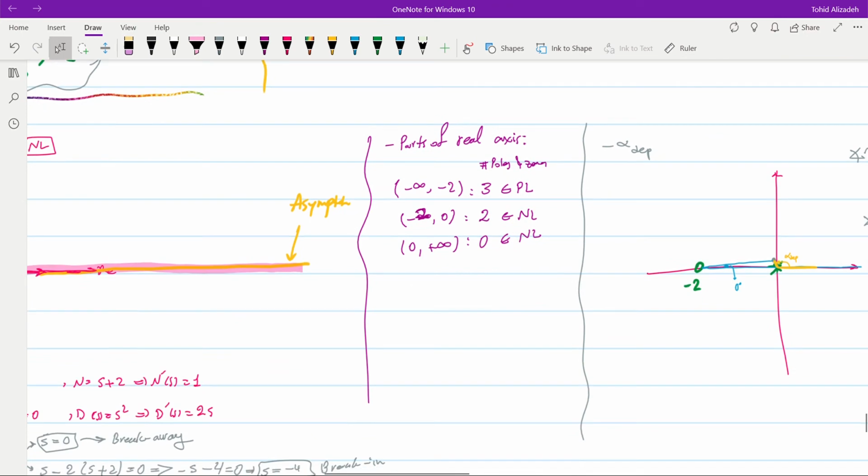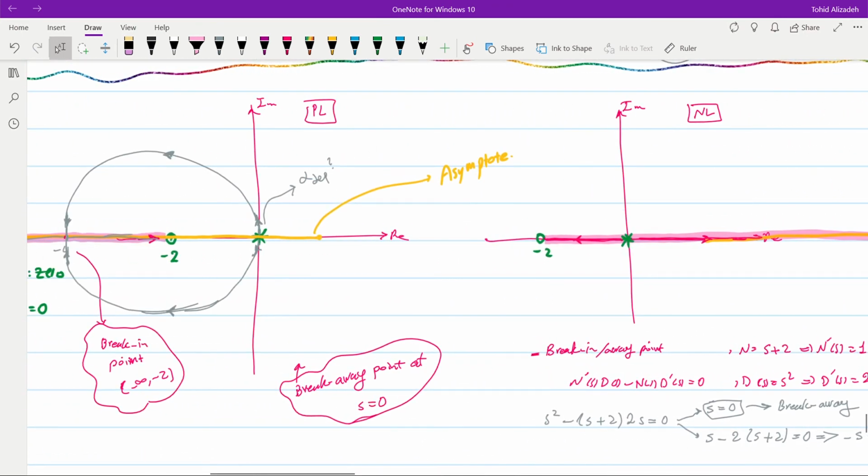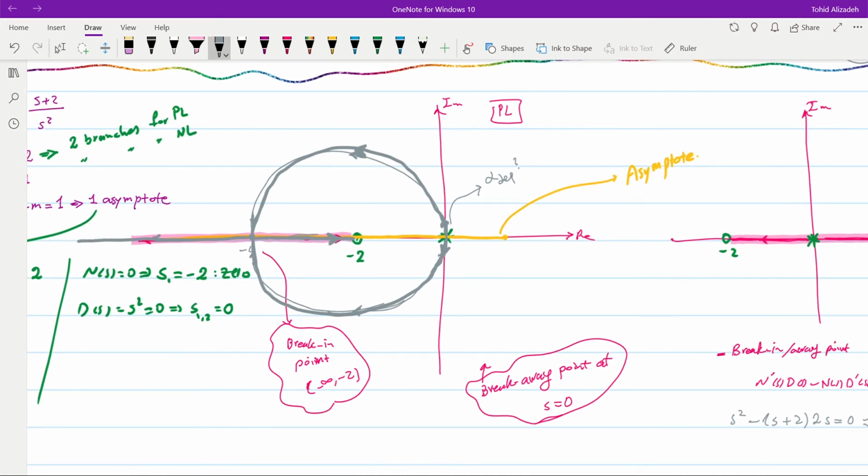And now if we go back to our graph, we could see that the branches will lie on the imaginary axis right at the beginning. The angle of departure will be equal to minus pi over 2 and minus 3 pi over 2. So this is not very neat, but I guess you got the point, yeah? They will enter into the real axis at the point minus 4. One will go towards the 0 at minus 2, and the other one will move towards minus infinity.